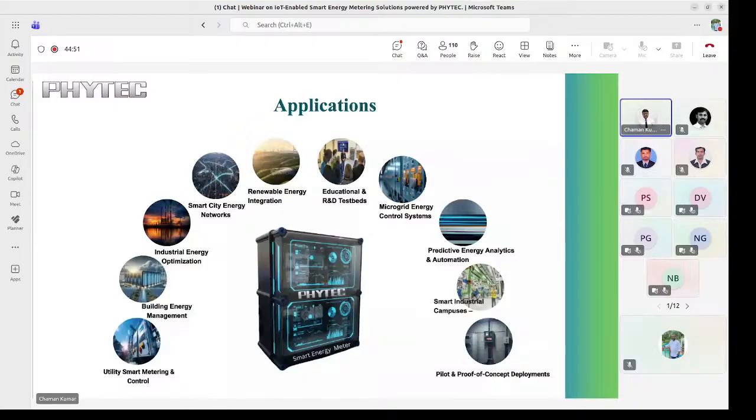Okay. Now we have to understand Wi-SUN. So Wi-SUN basically, if I say in my kit I am using the RF mesh, correct? So with RF mesh, for sending the data, connecting this meter to the DCU, we are using the Wi-SUN stack. Wi-SUN stands for wireless smart utility network. So it's an IEEE 802.15.4 based standard that will be IPv6 enabled.